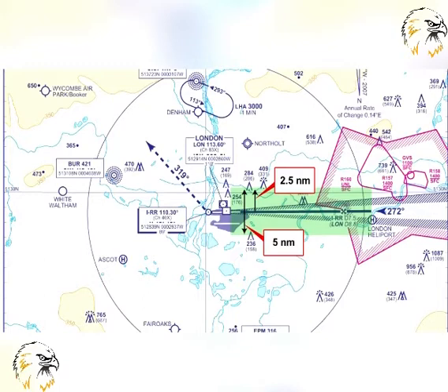Obstacle clearance could thus be provided by assessing the highest obstacle to be flown over, and by then applying a safety margin to that figure, an obstacle clearance height or altitude, OCH or A, could be obtained. This is the method of obtaining minimum safety altitude, MSA, and with refinements, minimum descent height or altitude for non-precision approach procedures. For precision approach systems, therefore, OCH or A is a range from threshold dependent calculation, and so it should be obvious that OCH or A for precision procedures is less than that for non-precision procedures.